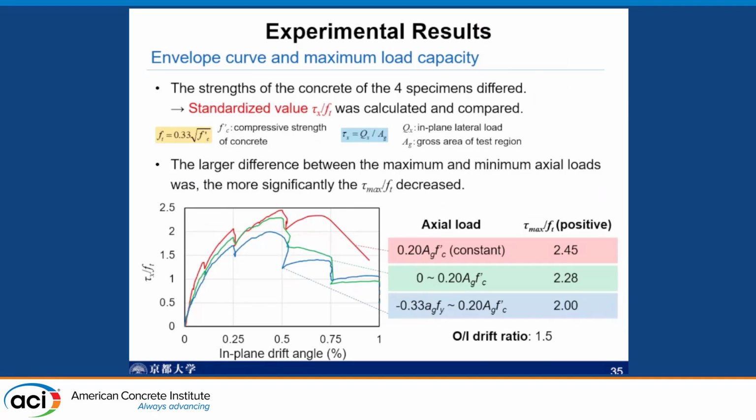So this figure compares the experimental results between 3 specimens, which had the same out of plane to in plane drift ratio, but the axial load ratio is different.